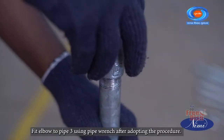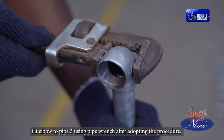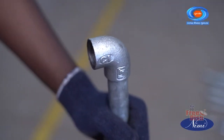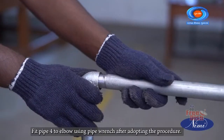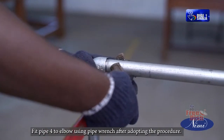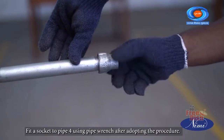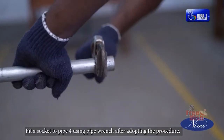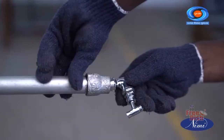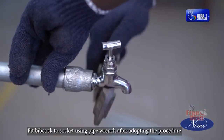Fit elbow to pipe 3 using a pipe wrench after adopting the procedure. Fit pipe 4 to elbow using a pipe wrench after adopting the procedure. Fit a socket to pipe 4 using a pipe wrench after adopting the procedure. Fit bibcock to socket using a pipe wrench after adopting the procedure.